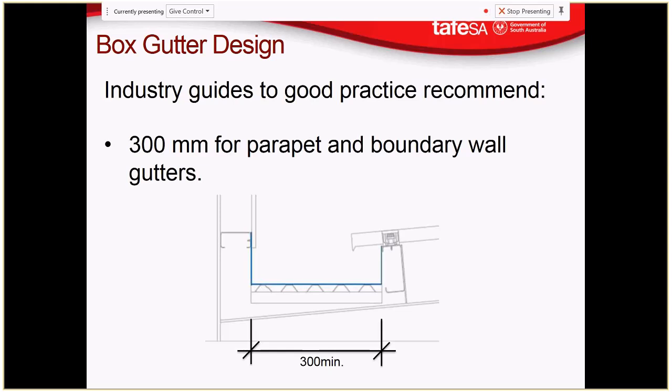And that's why it's good for the designer to be designing a box gutter as well. For them to go, oh, crikey, we don't actually have that 430. Let's go for a wider box gutter that's a little bit shallower, for example.